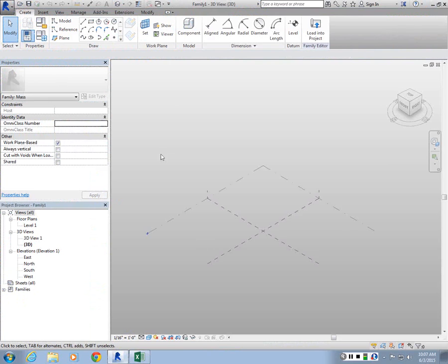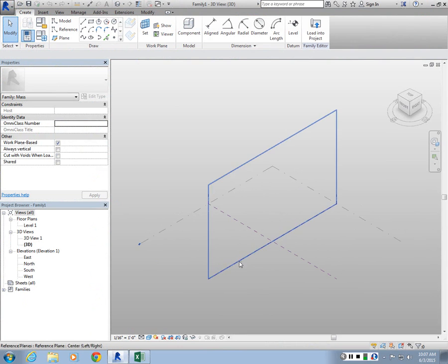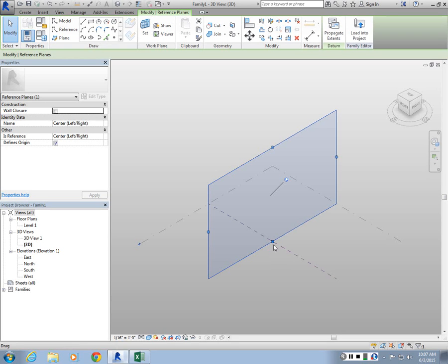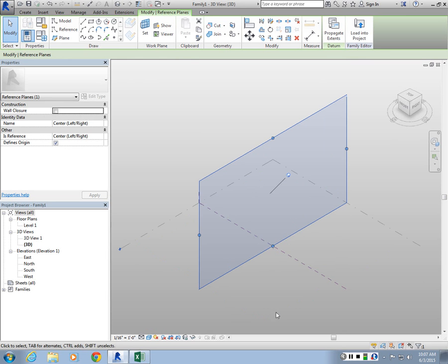Okay, so within the conceptual massing interface, what we have is basically our construction planes, where you could draw geometry. So in this case, we have two vertical planes which define kind of a fixed central axis, right? So there will be a line here where we could fix geometry. So you can think of like where the core of a tower could be placed.